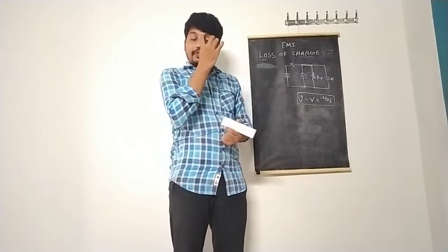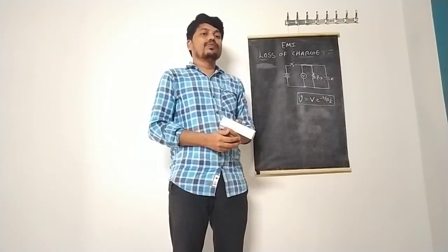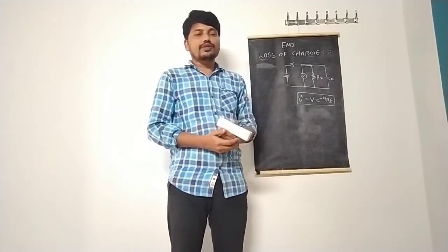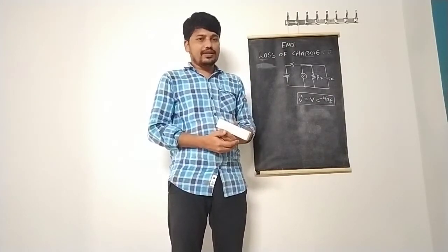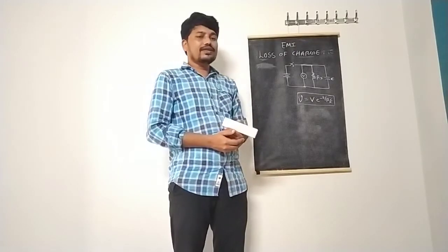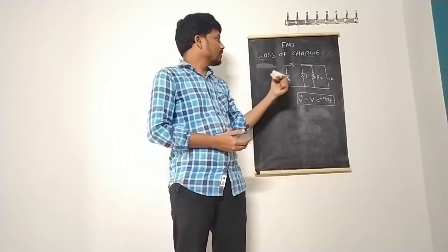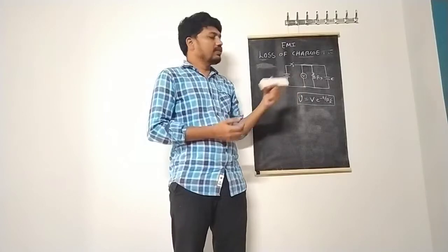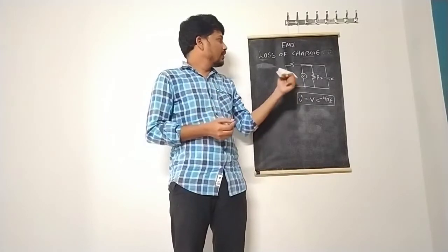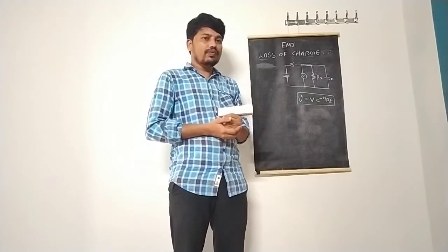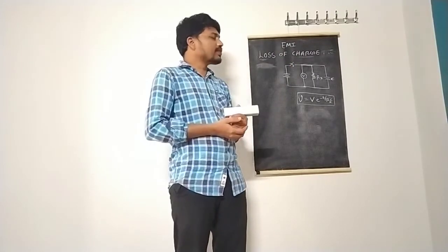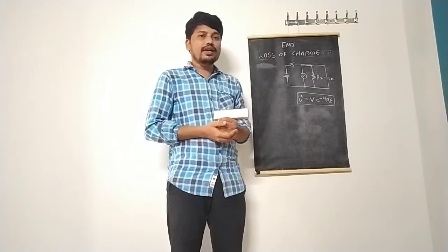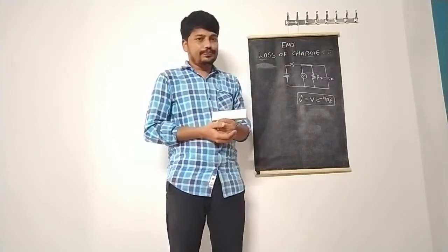So there are various methods available to measure this high resistance, such as high insulation resistance in cables or machines, and leakage resistance of capacitance. Many methods are there, out of which, to determine the leakage resistance of cables or capacitors, generally the loss of charge method is used for higher values. Therefore, my final conclusion is that the loss of charge method is a high resistance bridge method. In general, the value order is greater than 1 mega ohm.